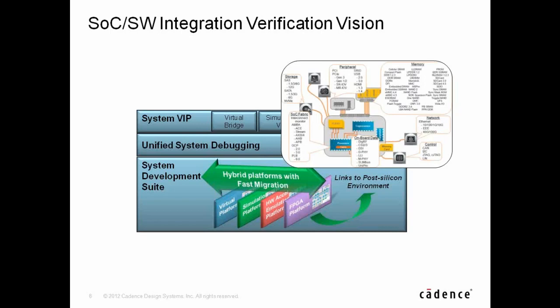We have things like virtual bridge, so this is where you would say, I'll connect the Ethernet of my host directly into the box. So you can actually now bring real-world Ethernet traffic. So it's the idea of connecting the Palladium into the real world. We already have something similar to this with speed bridges, which is a way of running real-time traffic into the Palladium. So things like HDMI, that kind of thing.